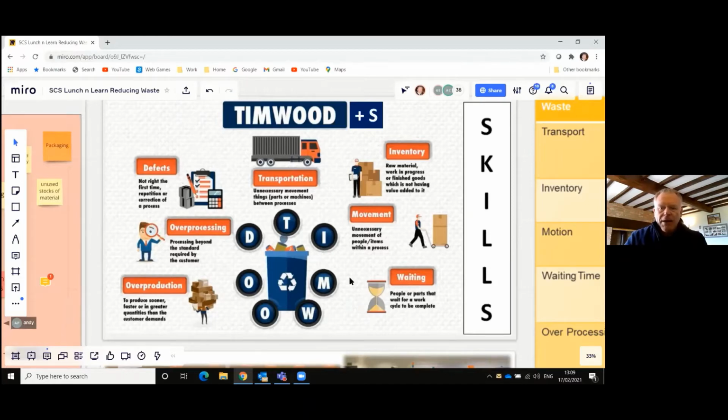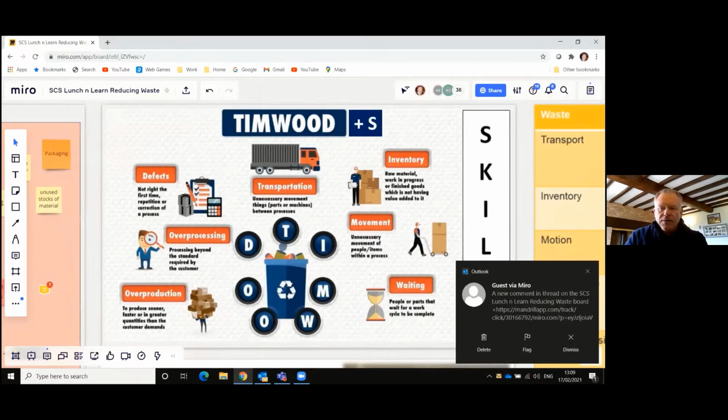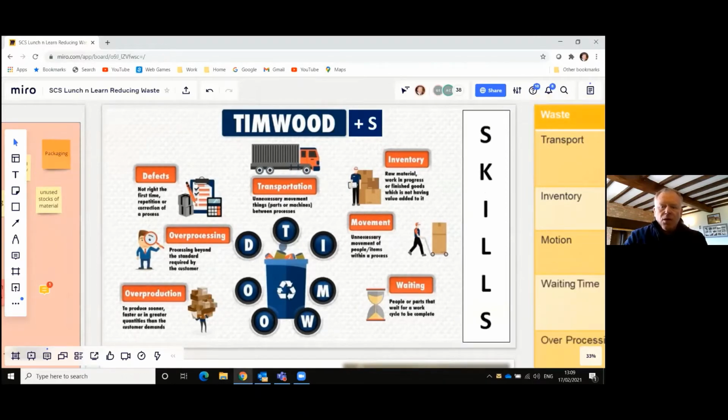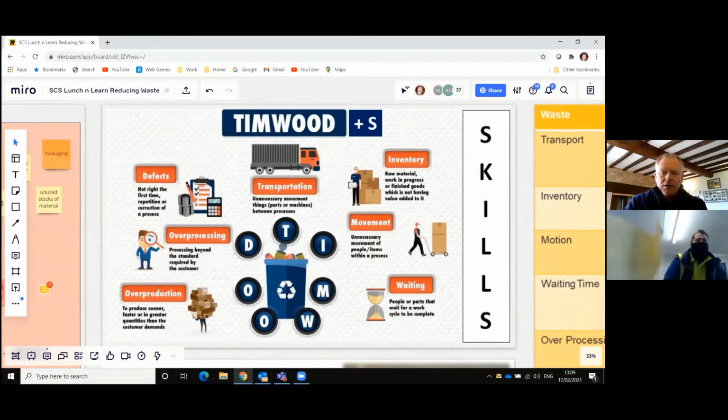Inventory is all about looking at what materials we need on site at any given time. Do we have the right inventory placed in the right place on site to be used right first time? Movement is all about the movement of our people. How do our people use those materials to create what is required on the site? Whether it be concrete supply, laying a slab, or metal supply to create the rebar for the structure.